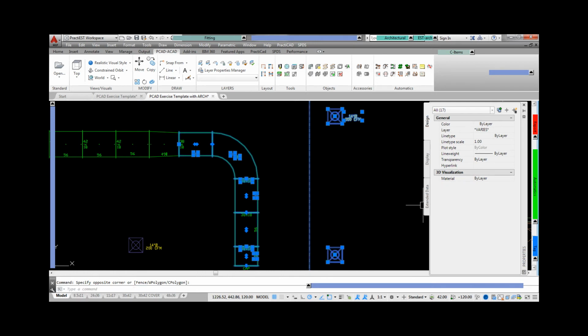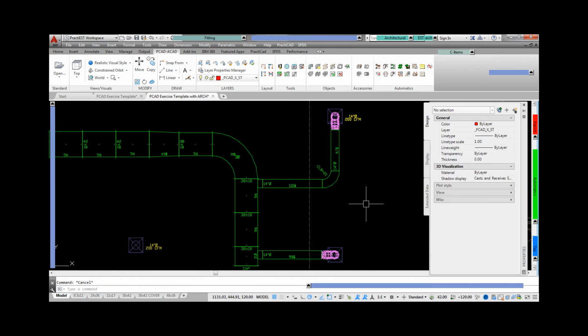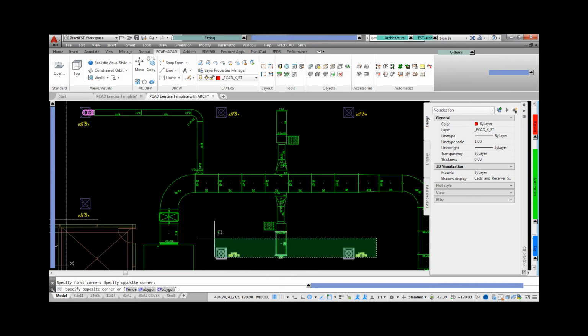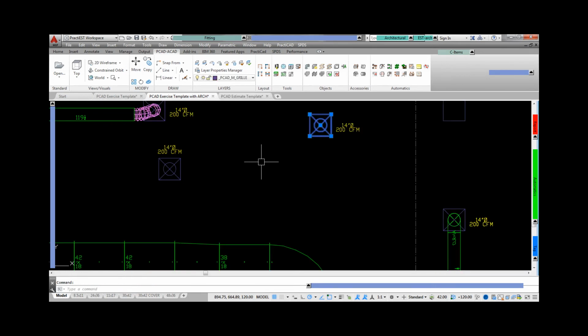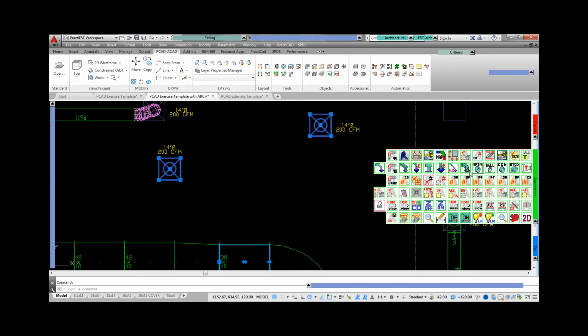This way we can report it later. Now we'll do one with spin collars as taps. We simply click the grills we want to use, select the fittings you want to route to, and it auto-fills immediately. Watching this next example use conicals, you can also see that we can window an area and PractiCAD will route to them all at once using the fittings nearest the grill. You can run as many of these at once as needed, and there's truly a lot of scenarios to choose from.